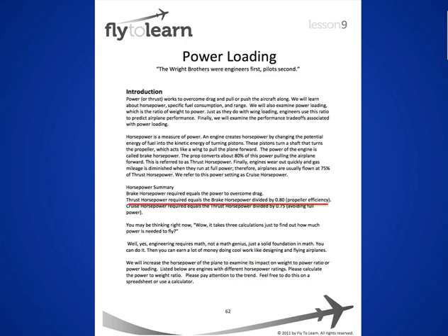Now, the next thing is, if that's brake horsepower, this was thrust horsepower, then you have a concept called cruise horsepower. Besides when you take off in an airplane, you don't ever want to run full power. It's going to wear out your engine. So you want to take that thrust horsepower and divide that by 0.75. And it increases the number yet again. So there's 3 calculations the kids have to do.